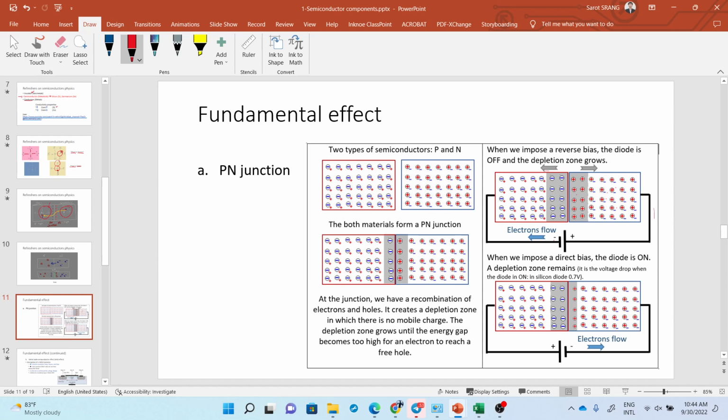And if you reverse the polarity, so the positive polarity connects to the p-type and the negative connects to the n-type, this one has excessive electron, right? And this one tries to attract electron. So this one attracts electron from here to here, and this one supplies more electron here. So in this way, it can conduct electricity, because this part is not going to run out of electron. Electron can be obtained from the negative polarity of the battery.